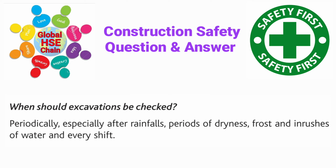Question is, when should excavations be checked? Answer is periodically, especially after rainfalls, periods of dryness, frost, and inrushes of water, and every shift.